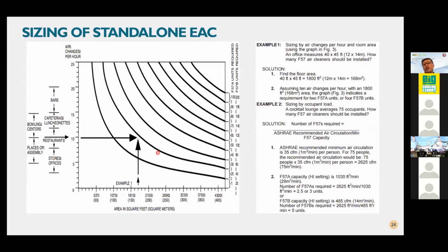For each equipment, you have a low speed, medium speed, high speed. Of course, we won't recommend high speed because of the mechanical fan. Just imagine a table fan, you turn it to high speed, speed number 3. Of course, you have mechanical noise, the fan airflow noise, which is sometimes quite irritating. The same goes for equipment like an electronic air cleaner. It has a fan, mechanical movement, so you may have some noise if you set it at a high speed. So the recommendation for office use, low speed or medium speed is good enough. From there, you can know how many units you require.